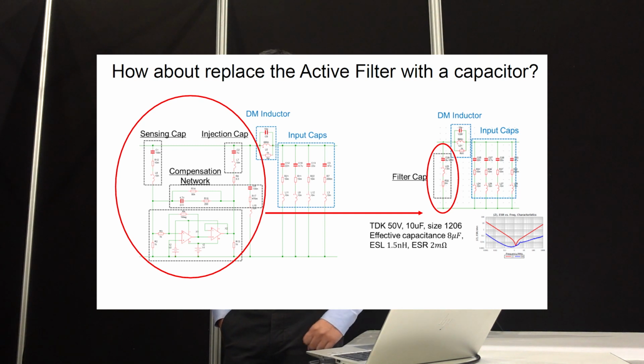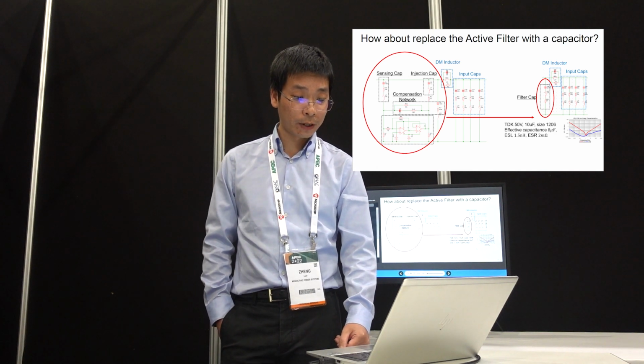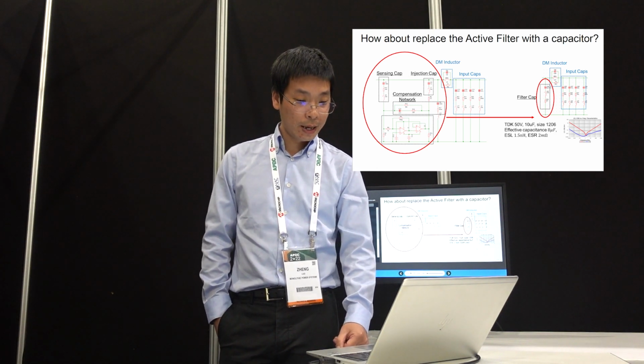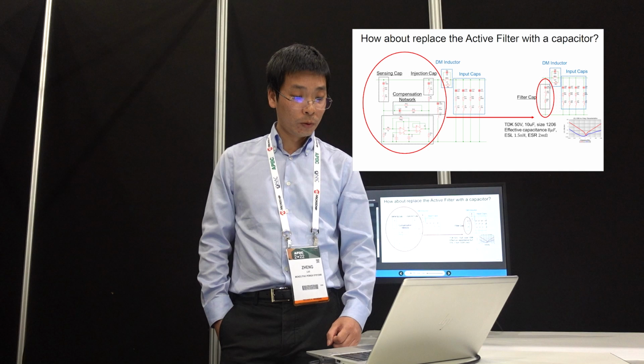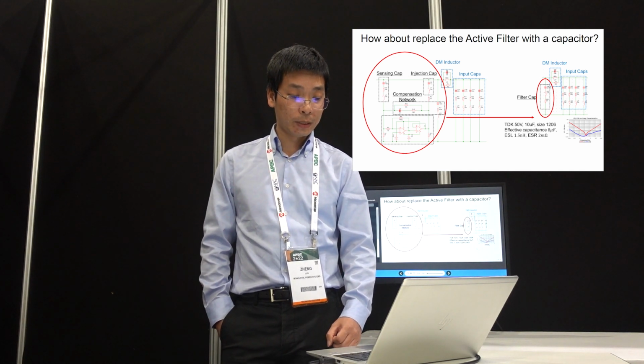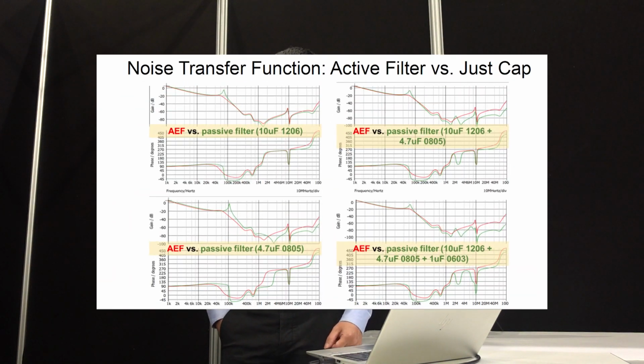So here is a comparison, and basically we build the noise transfer function for two cases. One case is with the active EMI filter, and another case is just with one cap. The cap we choose is a TDK 50 volt, 10 microfarad, size 1206, and the effective capacitance is about 8 microfarad in the 12 volt to 14 volt range. And we get the ESL and ESR numbers from the data sheet as well. We put it into the simulation, and let's compare the results.